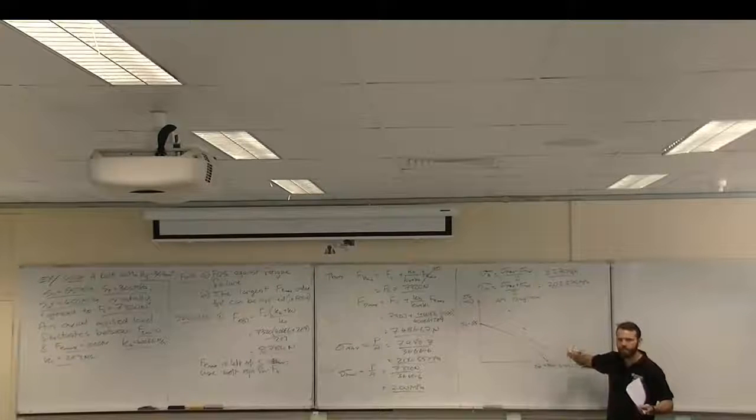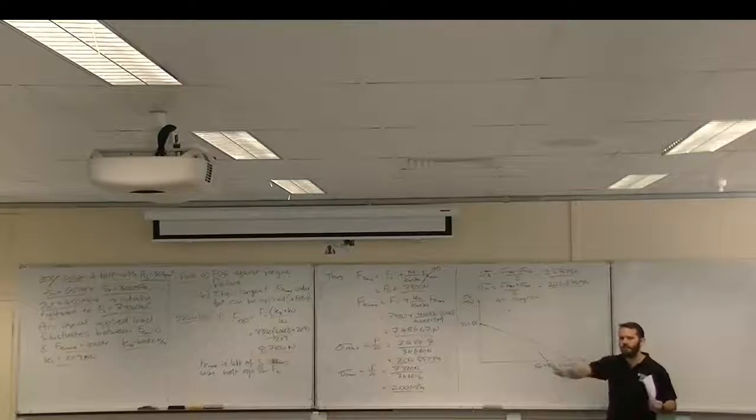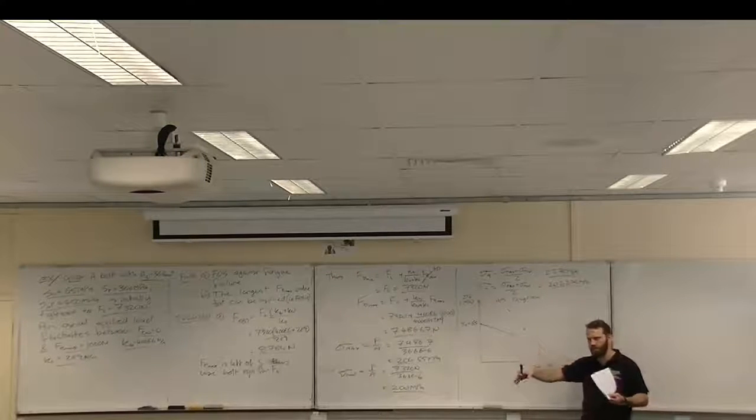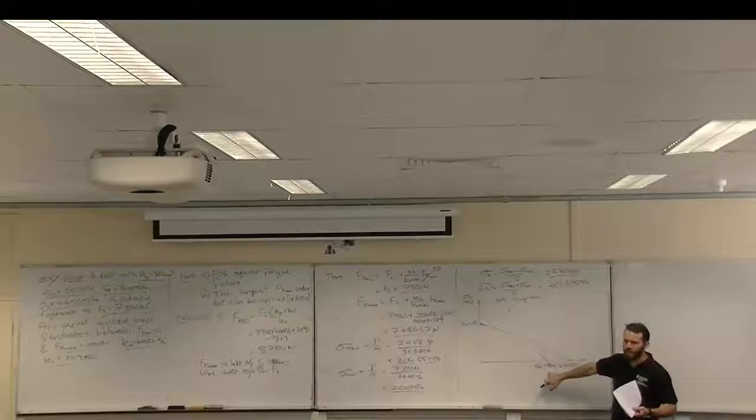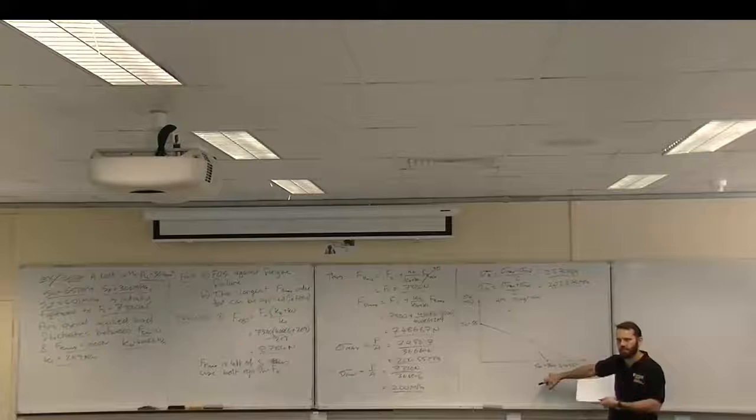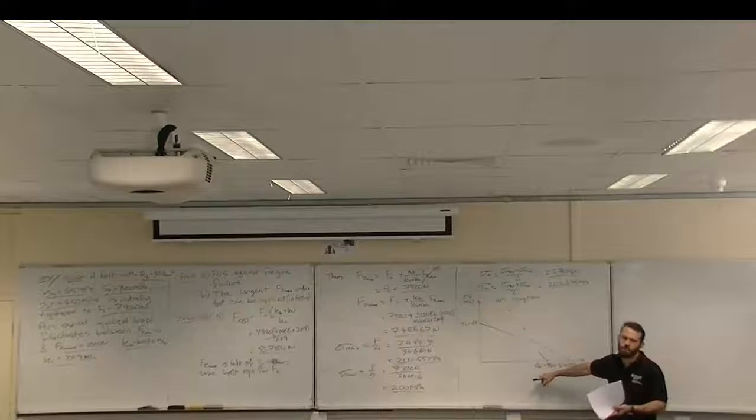Alright? So ordinarily, for any other component, yield is dictated by the static failure criterion that we use for shafts, wheels, etc. For bolts, our static failure criterion is that we're under proof load. So it makes perfect sense that instead of yield on this diagram, we use proof load on this diagram. And once again, as with everything in engineering, I've seen it both ways.